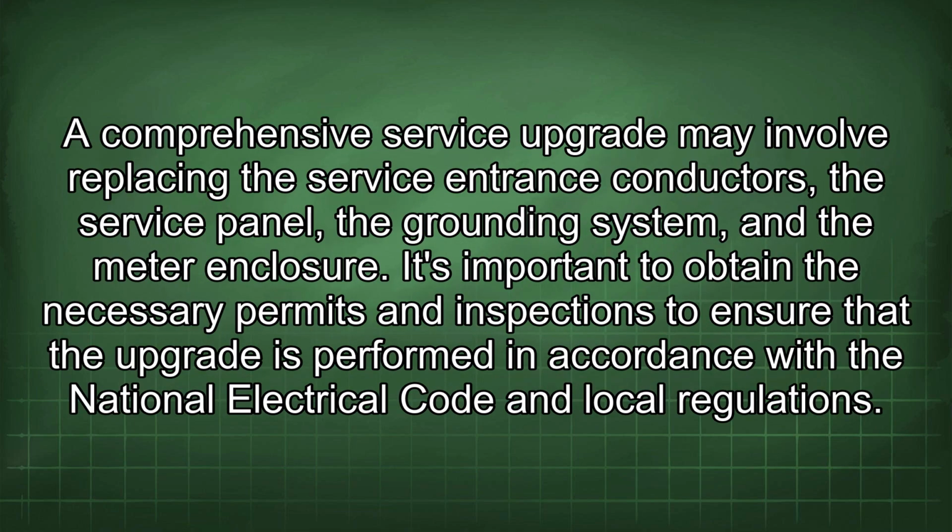A comprehensive service upgrade may involve replacing the service entrance conductors, the service panel, the grounding system, and the meter enclosure. It's important to obtain the necessary permits and inspections to ensure that the upgrade is performed in accordance with the National Electrical Code and local regulations.